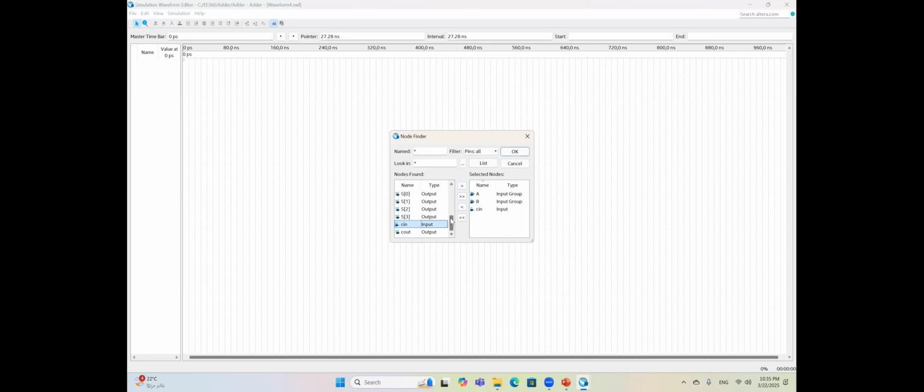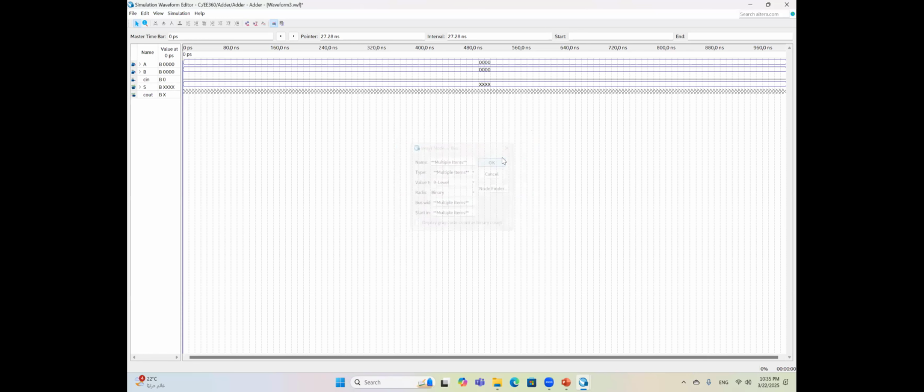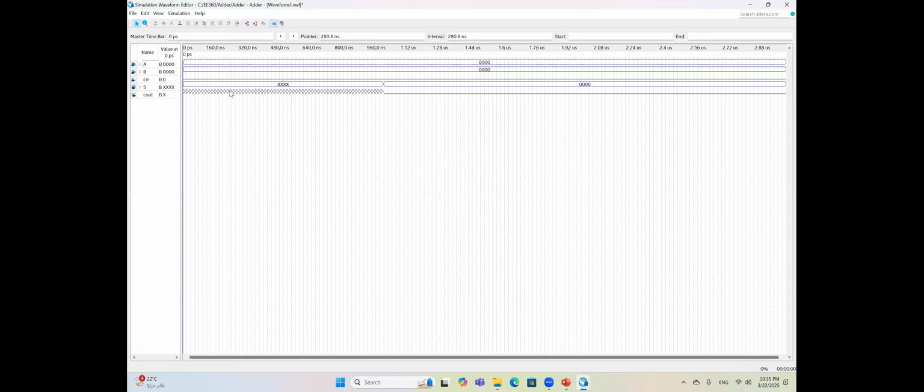And this will generate the sum and then Cout. Now, ready now, but say we'll use 3 cases. Go to Edit again, then set end time; we'll make it 3 microseconds, and then we'll set the grid size to 1 microsecond.